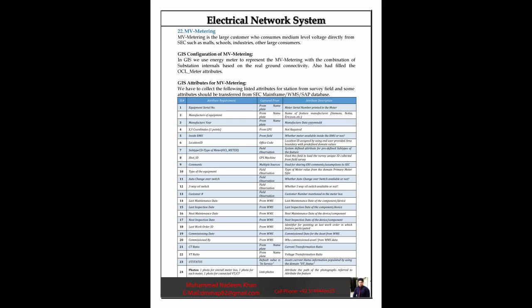22. MV metering. MV metering is for large customers who consume medium-level voltage directly from SEC, such as malls, schools, industries, and other large consumers. GIS configuration of MV metering. In GIS we use the energy meter to represent the MV metering, with the combination of substation internals based on the real ground connectivity. We also fill the OCL_meter attributes.